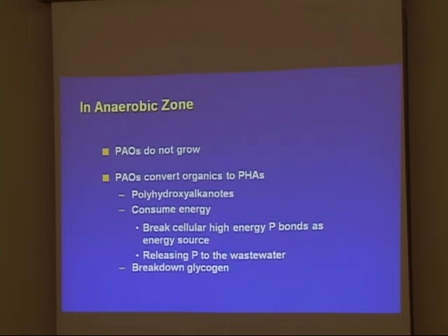Now, this is a lot of crazy stuff going on here. Bottom line, they're in an anaerobic zone. They're stressed. They are stressed out, and they are shedding phosphorus. They're not growing. And you think, but this doesn't sound good. You put these bugs through stress, they're dropping off phosphorus, they're making phosphorus. That doesn't sound like a good thing.